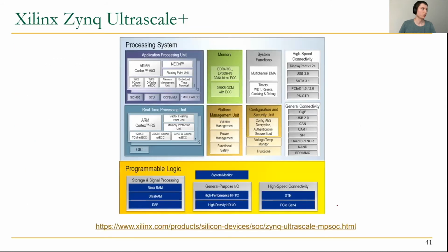And this is one example of such an FPGA. This is the Xilinx Zynq UltraScale+ FPGA. And you can see that it implements various blocks. It implements a memory controller to access DRAM. It implements some high-speed interfaces such as USB, DisplayPort, HDMI, and PCI, and other things. It even includes special blocks to do data encryption and decryption. And here you can see 2 processor cores are also inside the FPGA.